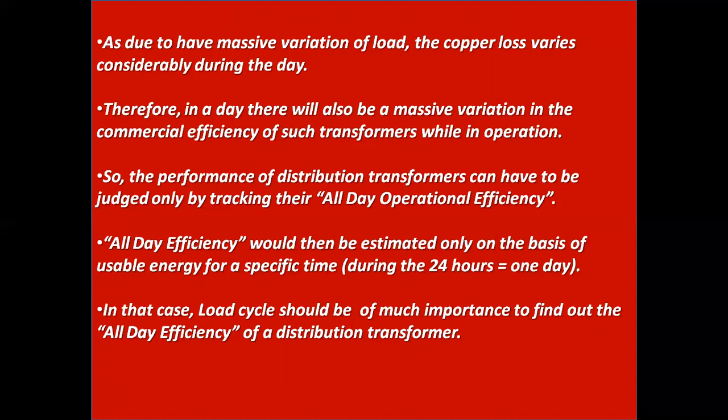So, the performance of distribution transformers has to be judged only by tracking their all-day operational efficiency. All-day efficiency would then be estimated only on the basis of usable energy for a specific time during the 24 hours, that is one day. In that case, load cycle is of much importance to find out the all-day efficiency of a distribution transformer.